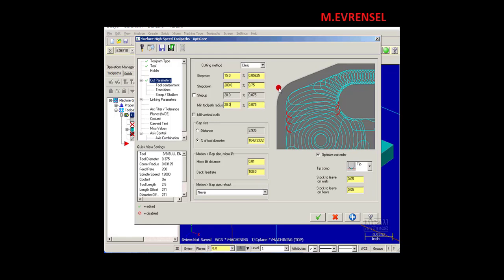This toolpath will never go in and use the full radius of the tool. It will always make an arc motion. That's what makes it possible to feed at an extremely high feed rate comfortably. So the toolpath radius, this generally is set between 20 and 40%. Let's just set this to 30%, middle of the road here. So in any corner situation, it's going to be cutting 112 thousandths radius. We're going to see this when we backplot the toolpath. So these three fields, step over, step down, and toolpath radius, are the keys for any dynamic milling.